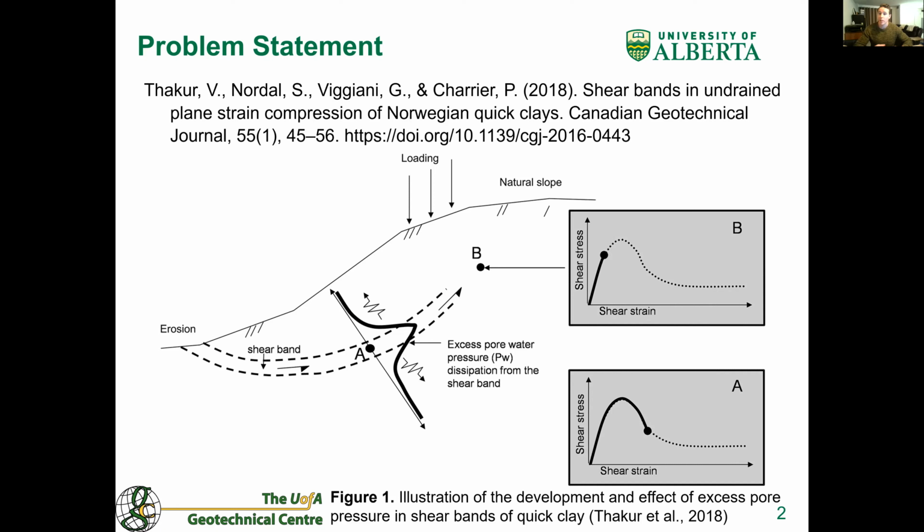As the shear band progresses upslope in the strain weakening material, the shear strength of the material decreases from either a pre-peak or peak, as with element B here, to either a working or residual strength due in large part to increases in pore pressures as seen at element A. These excess pore pressures significantly decrease the strength of this material throughout this shearing process.